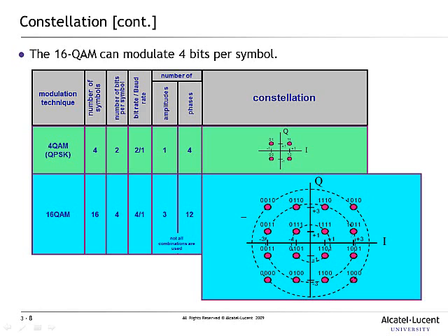We can have one of 16 possible phases transmitted in this situation. Here we are taking 4 bits at a time, and if you take 4 bits at a time, there are 16 possible patterns that you can end up with. Because we end up with 16 different patterns, for each one of those patterns we can send one of these phases.